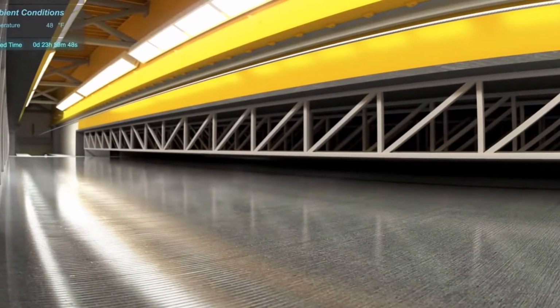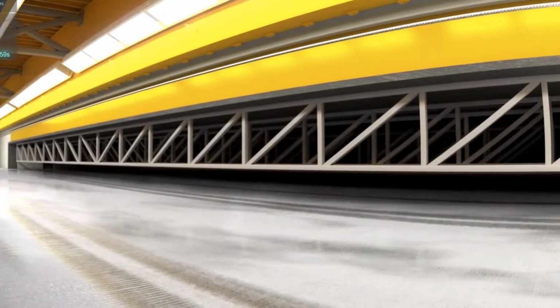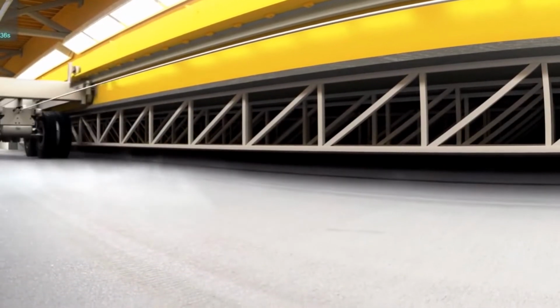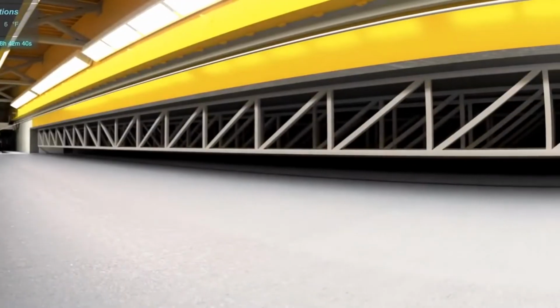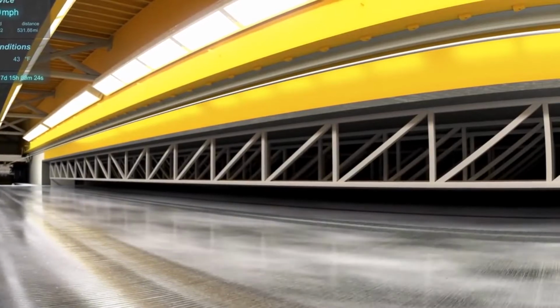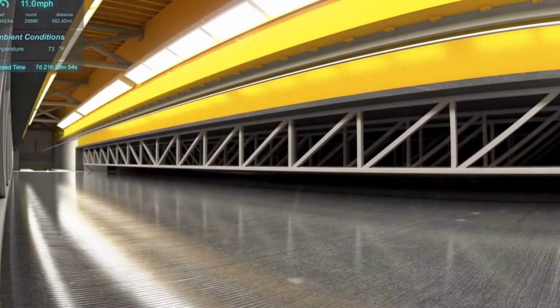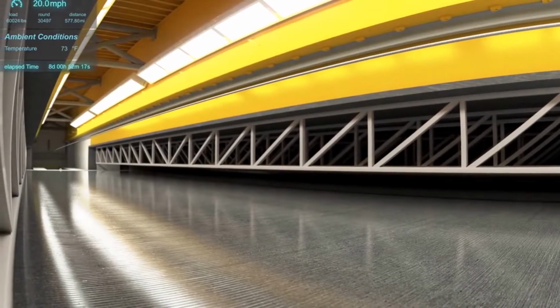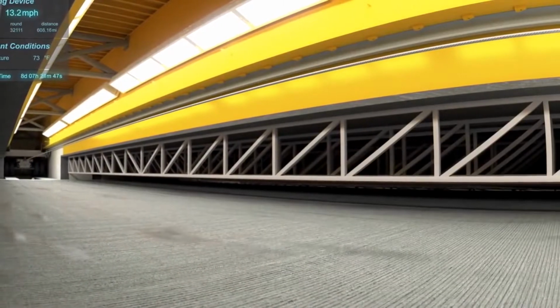And this is a little bit of an old animation. The precipitation is actually on the carriage now and gets sprayed out as it's driving back and forth. But we can apply just regular water. We can apply, again, de-icing chemicals up to 18% brine. We can cool it. We can heat it. And throughout all of this, we're running live loads, 17,500 cycles per day, right? It's not a fatigue test, right? When you add up these cycles, we're not getting millions of cycles.